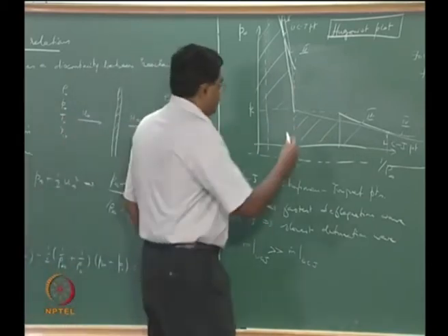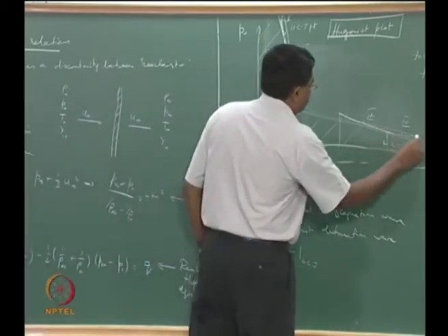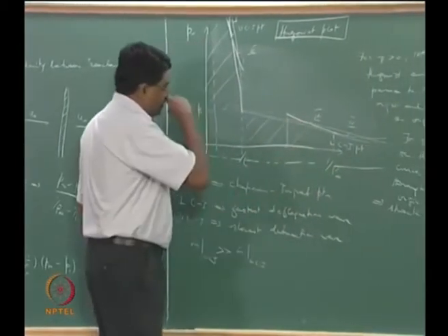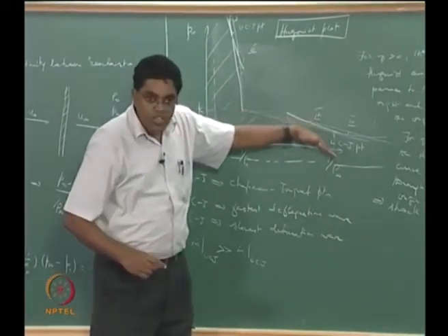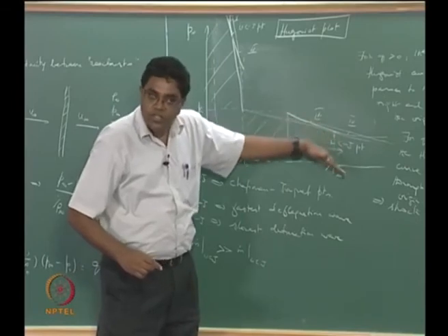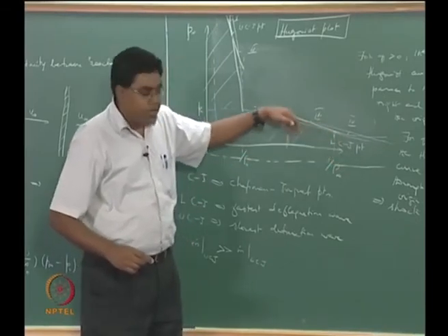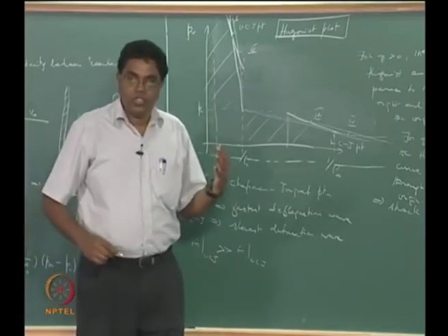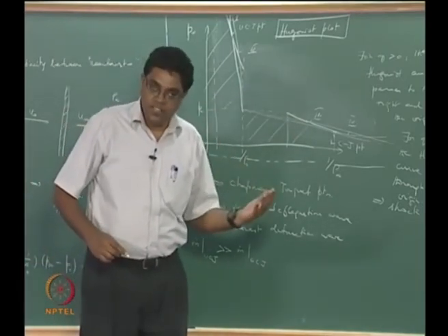Okay, so you are now looking at a Rayleigh line that is corresponding to a velocity that is still lower than the CJ deflagration, right. It is slower, and so correspondingly you are not really expecting a large decrease in pressure and density. Okay.